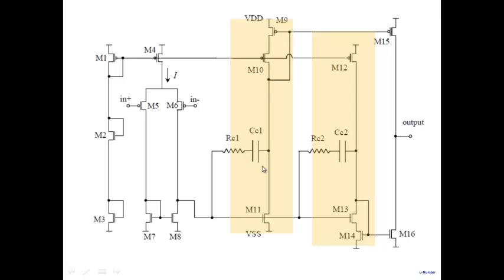So each one is a common source amplifier here, right? It develops a signal here and also develops a bias for M15. The signal that you have here gets amplified and appears over here. Common source amplifier, and through this it goes into M50. And this circuit here also generates a bias for M50.